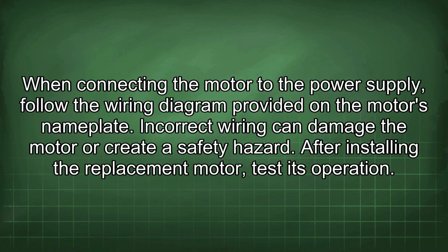When connecting the motor to the power supply, follow the wiring diagram provided on the motor's nameplate. Incorrect wiring can damage the motor or create a safety hazard.